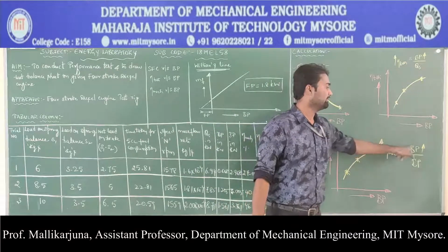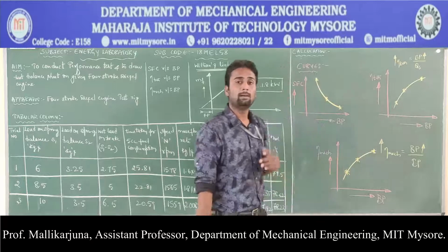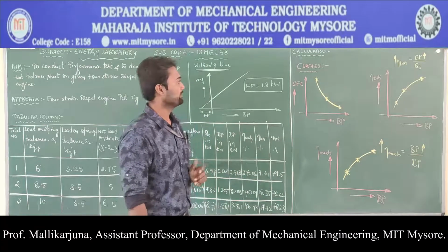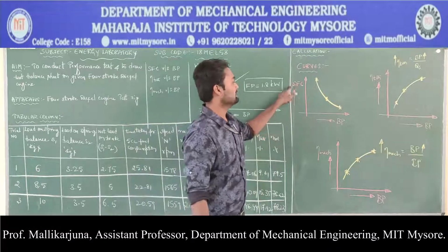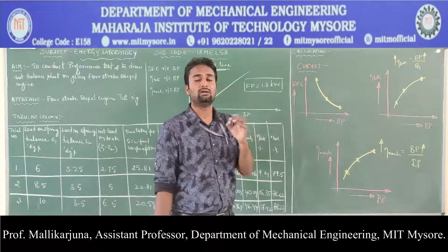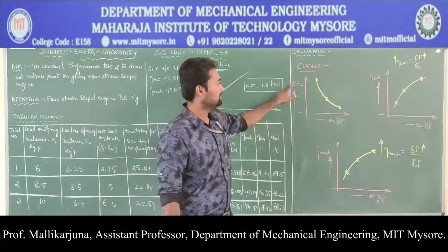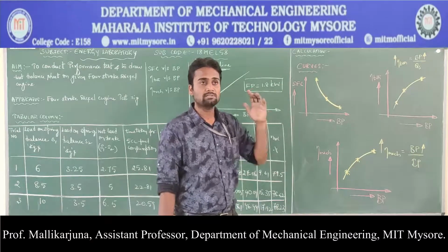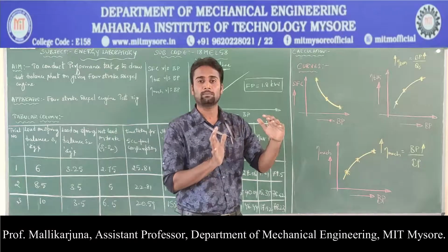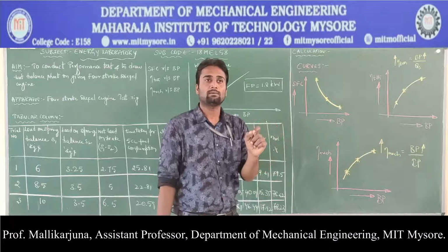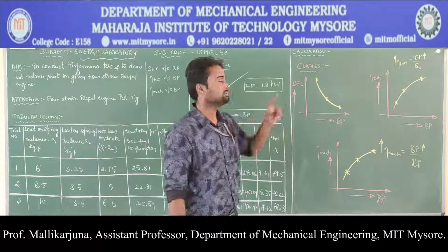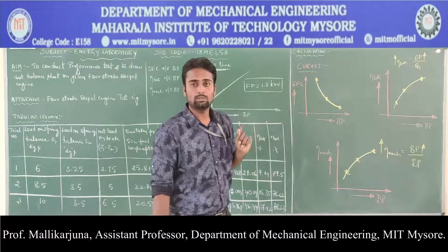That means mechanical efficiency is directly proportional to the power developed by the engine, which is nothing but the BP. And the last curve is SFC versus BP, where SFC is nothing but specific fuel consumption. Specific fuel consumption definition says amount of fuel consumed per kilowatt power developed. 1 kilowatt power development is going to consume how much fuel, that is what SFC is going to say.